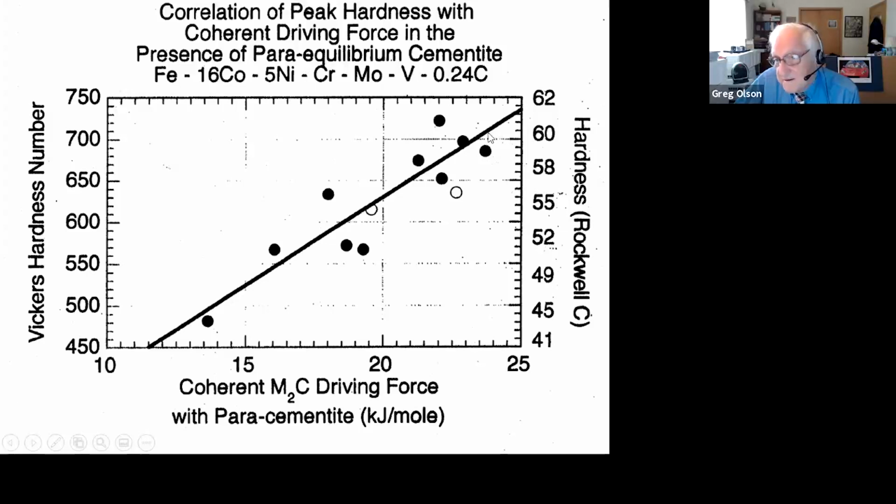could vary the hardness, peak hardness of this strengthened steel over about 20 points on a Rockwell C scale. So very dramatic, direct proportionality predicted by the model. And so that calibration became the principal tool that we used to design steels with much more efficient strengthening, demonstrating alloys that for a given carbon content could have 50% more strength than the previous technology. So it's an area that's been highly developed empirically, but in fact, there was a lot more to be achieved by being more predictive and taking systems to a high level of optimization using these tools.